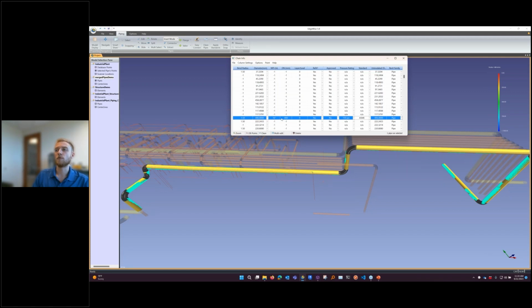So when we export to E3D, we will have this information in the equipment name, and then the outside diameter will be the actual diameter that's defined here. We'll see that once we go into E3D, but this is how we deal with specs. We do a lot of the modeling, and once we've got stuff set up, we can apply that intelligence to say, you're this, you're that for the nominal values.